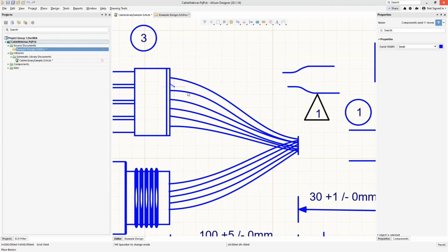Now just do something like this. So here's my first point. I've clicked once. I'm going to click a second point, a third point, and then I'm going to bring in my fourth point. Now, after I brought in my fourth point, notice that that wire is light blue, not dark blue, because if I left mouse click again, it's going to try to draw this as the first point moving forward, and I don't want that. So I'm going to right mouse click, and it now takes this as the new Bezier curve. If I want to continue with another point somewhere else, I can do so, but I'm going to right click again just to end it.